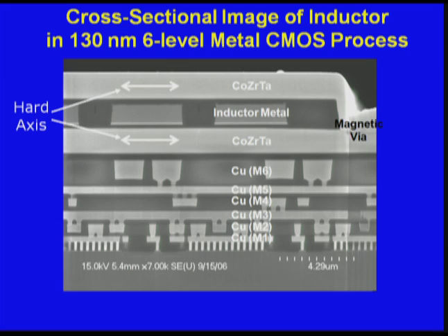And then on the right here, you'll see what we call a magnetic via. Now, we call it a magnetic via because it doesn't have to have current going through it like a traditional via does. But you do want to get that magnetic flux to go around it. In fact, if you have current that goes around here, that's actually a bad thing. That means you're introducing more eddy currents. So ideally, you don't want to have too much current flowing in that part of the structure.